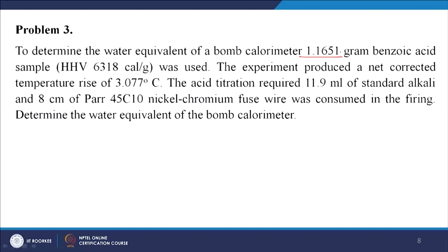Now, we are coming to problem number 3. The statement is, to determine the water equivalent of a Bomb calorimeter, a 1.1651 gram benzoic acid sample, high heating value 6318 calorie per gram, was used. The experiment produced a net corrected temperature rise of 3.077 degree centigrade.